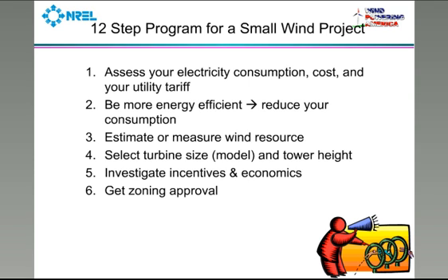Estimate or measure your wind resource. Typically, for a small system, internet search is all that's really worth doing, or calling your airport or whatever. Only when you're getting to, say, 50 kilowatts or 100 kilowatts or bigger, do you want to start thinking about maybe measuring your wind resource. And it depends a lot on how much uncertainty you're willing to tolerate. Start selecting some candidate turbine sizes and models, and get an idea for what you want to get.